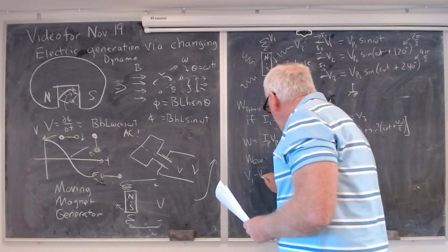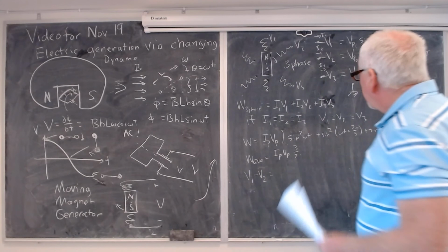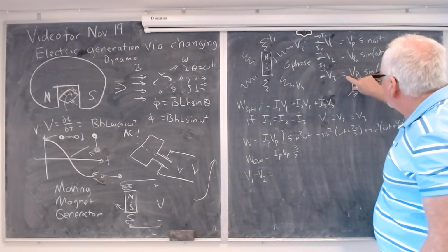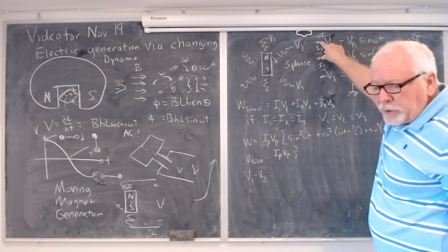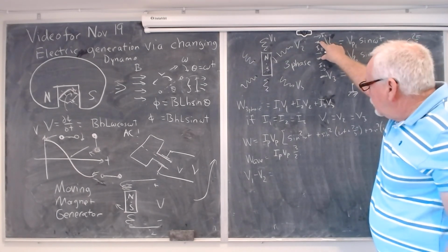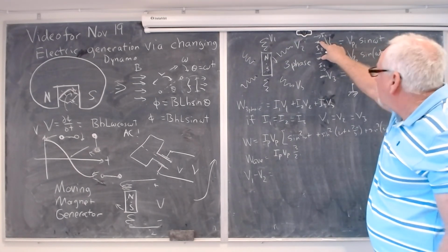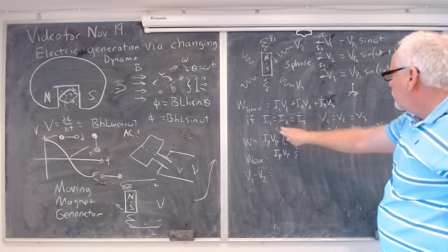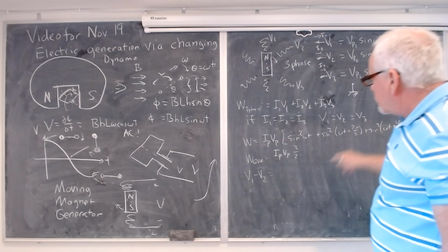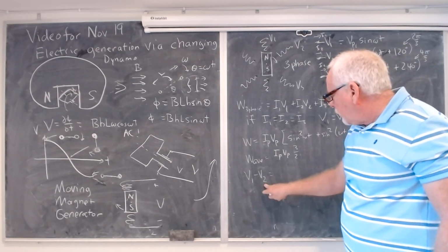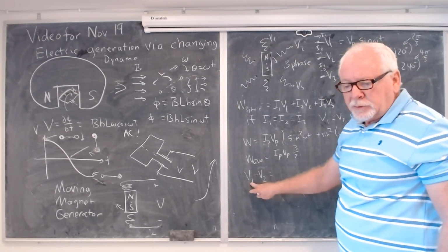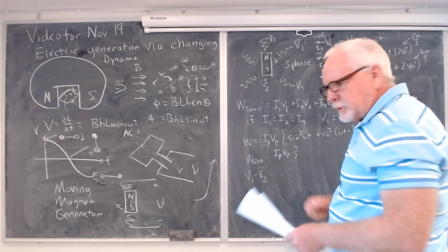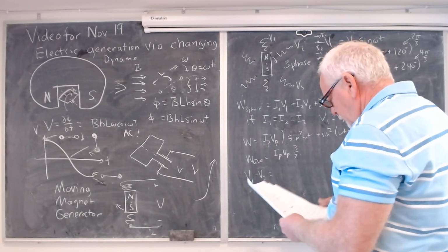if I take V1 minus V2, now what am I doing here? Instead of measuring each one to ground, I'm going to measure between two of the phases instead. Now, does it matter which one? No, because they're all the same. I set that up in the problem. I said they're all the same. So the fact that I'm writing 1 and 2, it could be 2 and 3 or 1 and 3, it doesn't matter. Just any two of the phases, I measure the voltage between them.